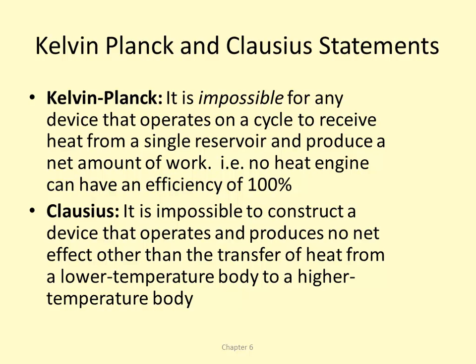Kelvin Planck statement and the Clausius statements are equivalent statements of the second law. It is impossible for any device to receive heat from a single source and produce work. So in other words, no heat engine can convert 100% of heat to work. And then the Clausius statement is that it's impossible to transfer heat from low temperature to high temperature without putting work into the system.